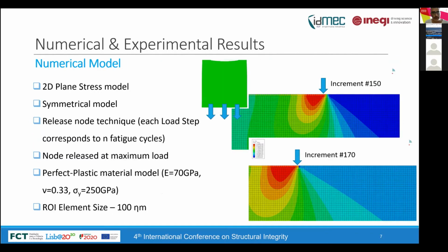In order to simulate not just the final static loading of the cracked specimens, we also wanted to simulate the whole fatigue process of the specimen, because during this fatigue test, as we know, there will be plastic strain accumulation along the crack front. And we wanted to capture this effect in order to compare it with the experimental results.